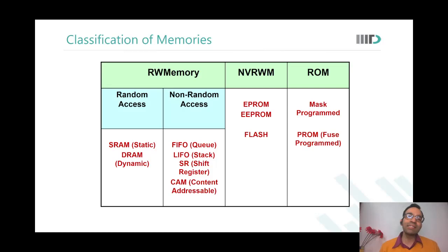So in content addressable memories, you give the content that you want to find. Let us say there is a memory which stores names of all the students in this class. And someone wants to see: is there a student named Akash in the class or not? And then they may need additional information. What is Akash's roll number? So we have the content available with us.